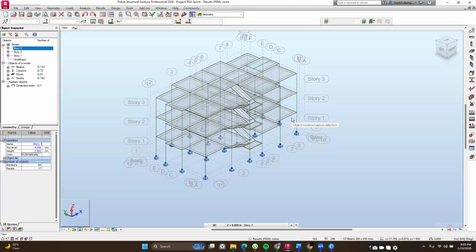And then it is going to analyze all the forces at all nodes and then extrapolate them to get the design, or it will also calculate the forces at every node. So for you to design using Robot, you have to ensure you set those finite element settings or the meshing settings correctly. Okay, it's really, really important.